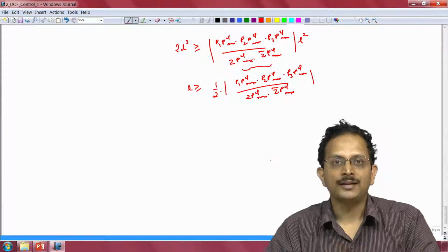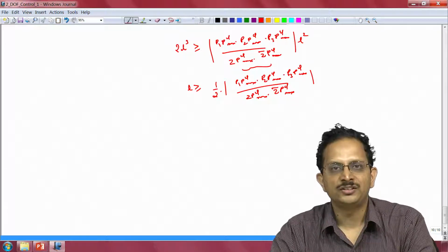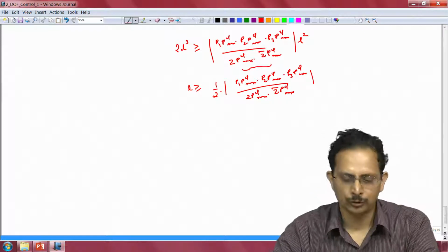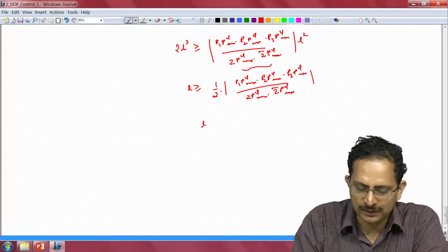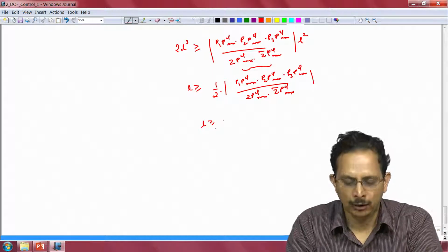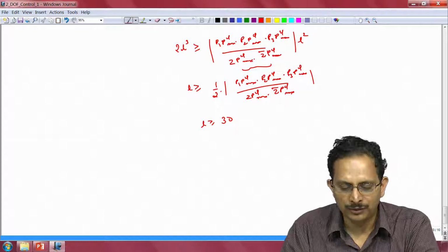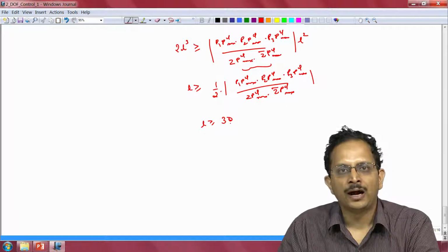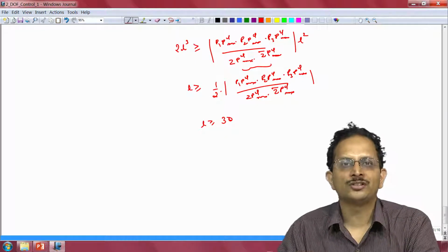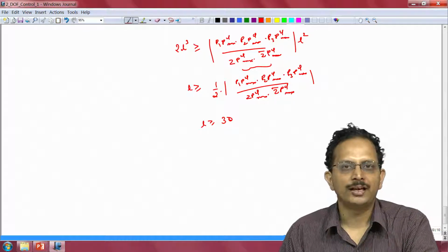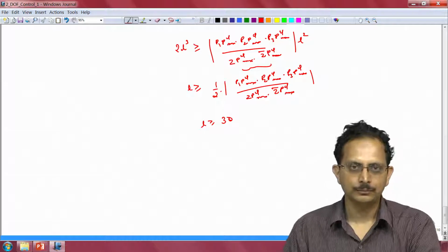Now if you plug in the values for PCL max and P1 and P2 and Z bar and P3 and so on, we would get that the distance L should be greater than or equal to 30. So our poles P4 and P5 should be at least 30 units away from the imaginary axis on the negative real axis of the complex plane.